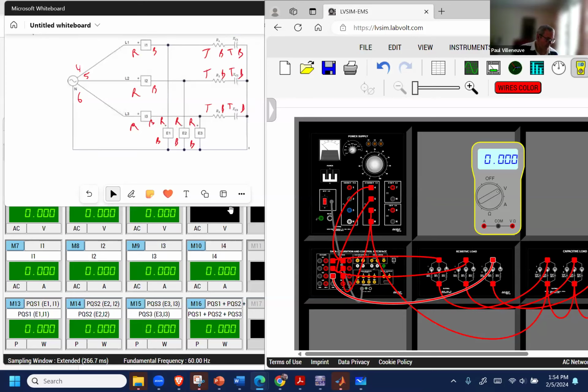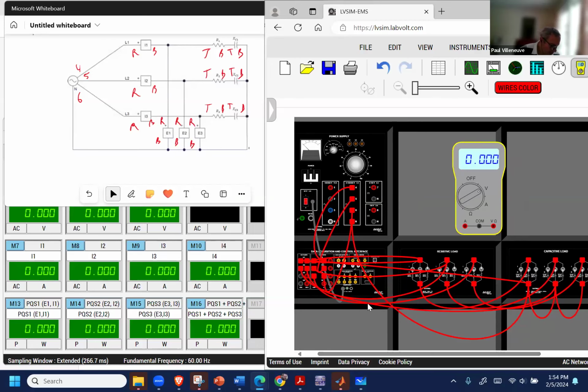Now the only thing I need to do is measure my voltages. And you can see I'm just checking across the resistor and the capacitor combination, to neutral. So I'm going to run over here. That's my first. Oops. My second is here, that one resistor, and this one over here. So again, just trying to be consistent. And then for my last one, I've got to move some wires out of the way. I'm going to run to this resistor top. Oops, didn't like that. I guess I did a bad job of connecting it. And to the bottom of this capacitor.